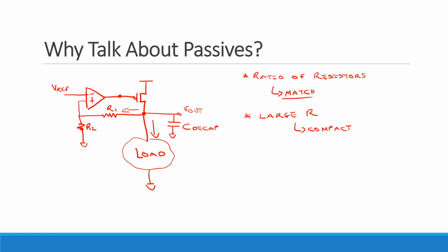Because especially if I just built this out of some, let's say, common source amplifier. So obviously this is not exactly it, but conceptually something that looks like that. It's a high impedance node, right? So I'm going to need some sort of compensation network. So what's a common compensation network I might use? Okay, you said a Miller cap. I think you said an RC, right? So actually let's go and do some RC thing like that.